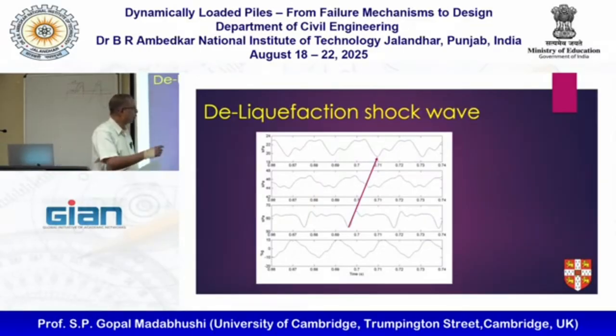And because it's a P wave, that is, a pressure wave, you can work out lots of other things. If I know the P wave velocity, I can tell you the degree of saturation and all kinds of other things. Skempton's B parameter and other soil mechanics related stuff also falls out of this. But the biggest thing here is what Cutter and Balakrishnan said, the liquefaction shocks. We can observe them directly from the data.